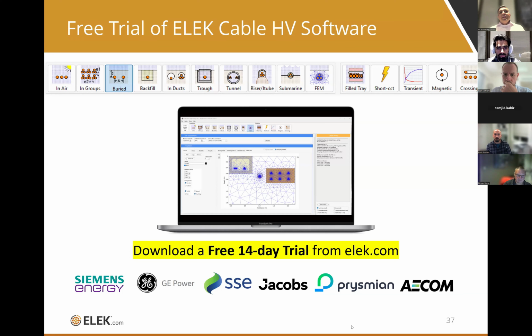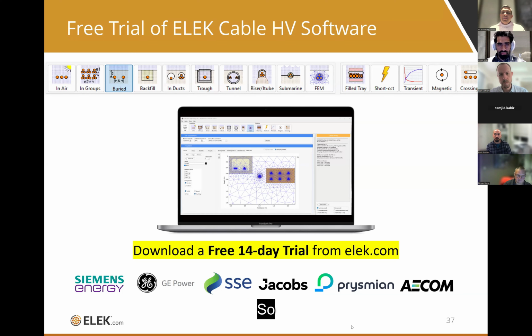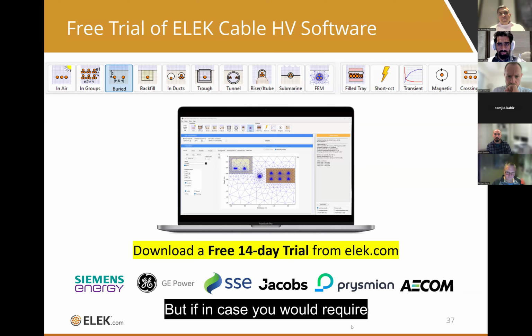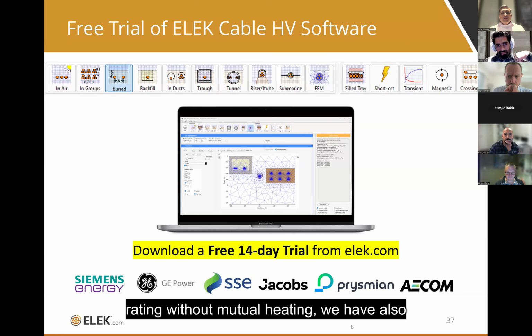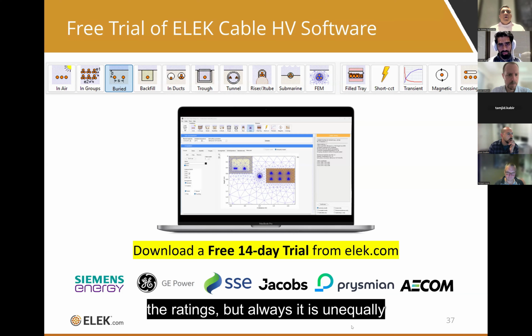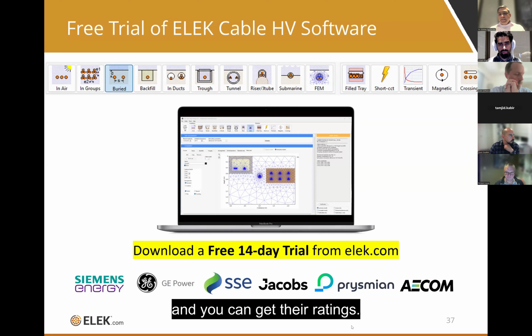We have seen a 10 to 15 degree temperature rise because of mutual heating between cables, especially when cables are buried deeper. So in our software, CableHV, we always consider mutual heating between circuits. But if you require a rating without mutual heating, we also have an option to select that, where you can ignore mutual heating and get the ratings. It also handles unequally loaded cables, and you can get their ratings.